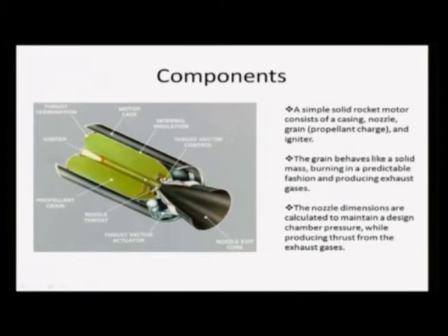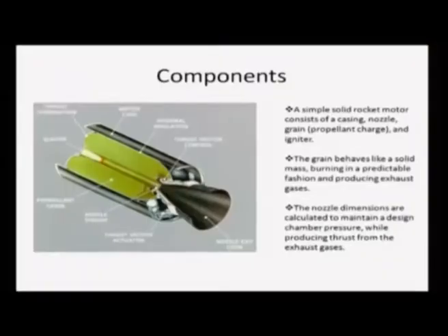I will discuss the igniters in detail. So, this is the igniter which will initiate the combustion process, because this is a solid propellant. They are fairly closely packed and a lot of initial ignition energy is required to start the ignition process. Once that starts, then it will burn on its own, but the initial ignition requirement is quite high. Therefore, the igniter is a must to provide that initial ignition energy. Apart from that, of course, the thrust has to be terminated somehow. So, you can see at this end there are some plates which work as the thrust terminator.